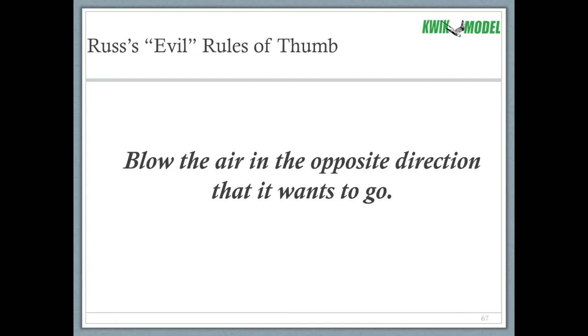The rule of thumb I like to tell people is blow the air in the opposite direction that it wants to go. So if you're blowing air into the room, the natural direction that air wants to go is out of the room, because you're pressurizing that room with air, so the air wants to leave. So if the natural path of air is to leave the room, blow the air in the opposite direction. Blow it from the door towards the other side of the room. What that does is it promotes mixing. The most important part of a supply register's job is to mix the air in the room. Okay, so blow the air in the opposite direction that it wants to go.